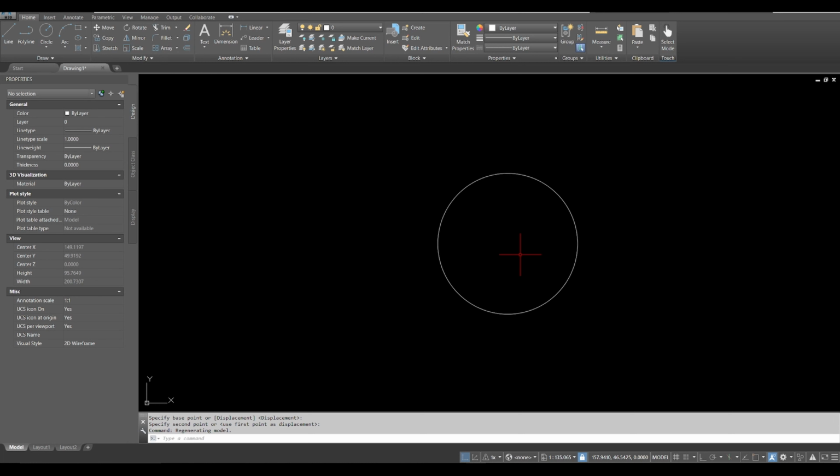In my experience, I have found that changing the middle mouse button to use the snap menu is significantly faster. Pretty much everyone I know who is a top tier drafter uses this technique. It's one of the things that sets them apart from their competition.